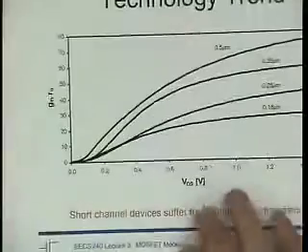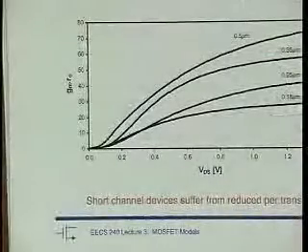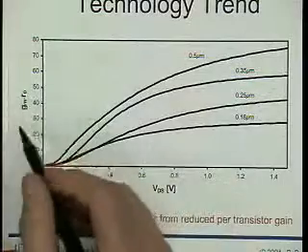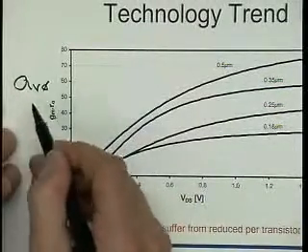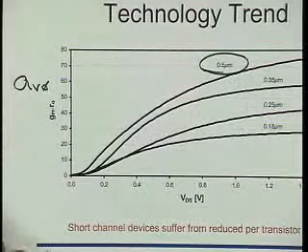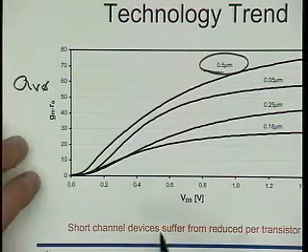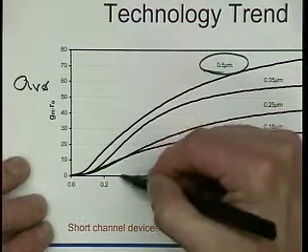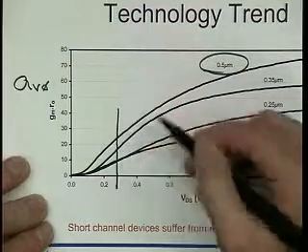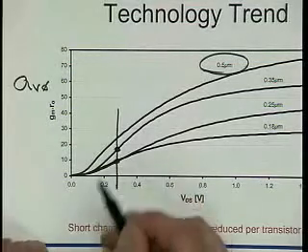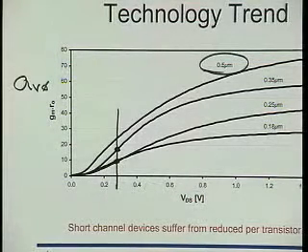Okay, technology trend again. Here, same business for minimum channel length devices over a bunch of technologies. And now, so this is GMRO, so this is AV0. And now, finally the 0.5 micron is the winner. And 0.18, well, it's not that much gain, right? If we want to have a VDS of only 300 millivolts, for example, then a gain of about 10 apparently. And here it's just about 26 or 27, like we had on the other slide.